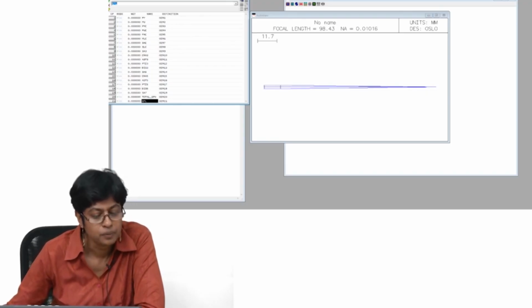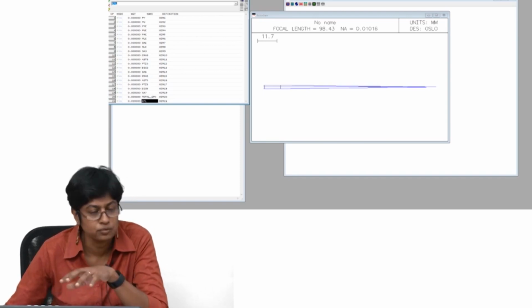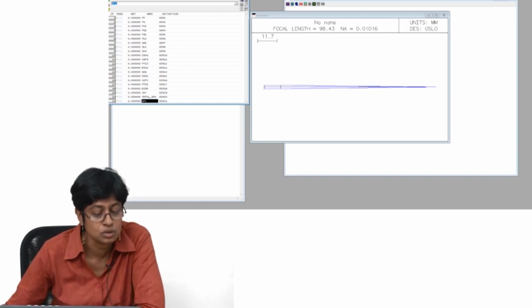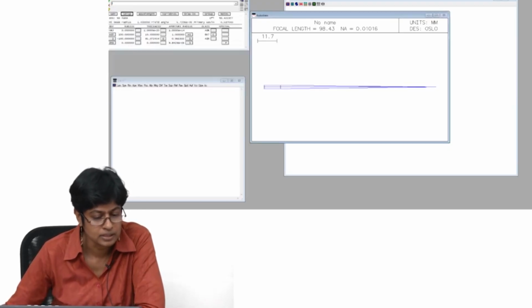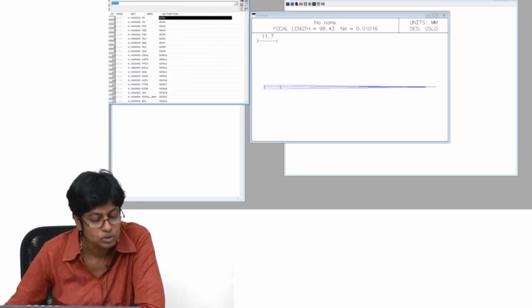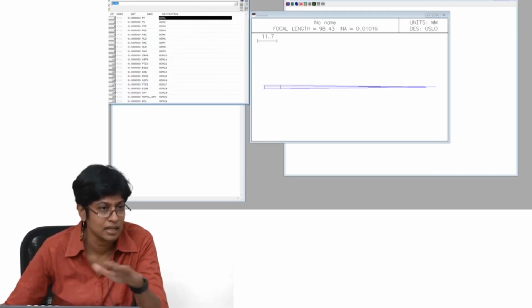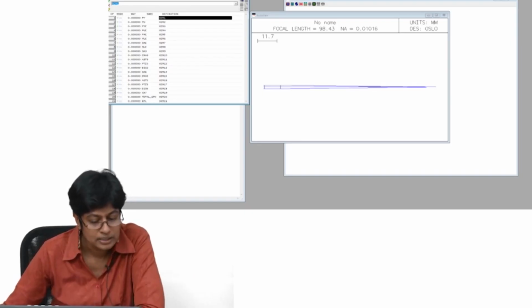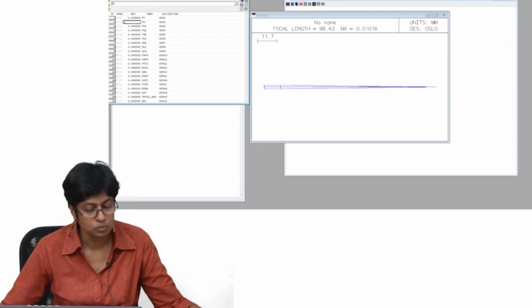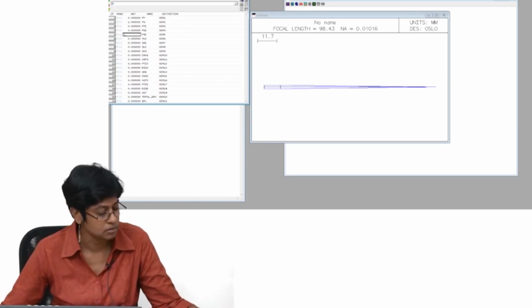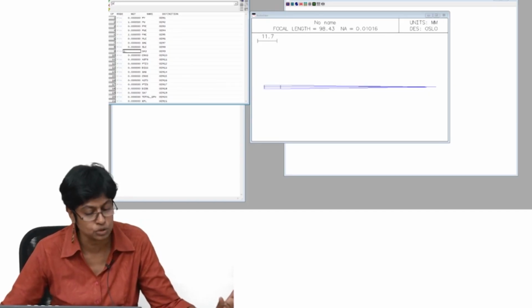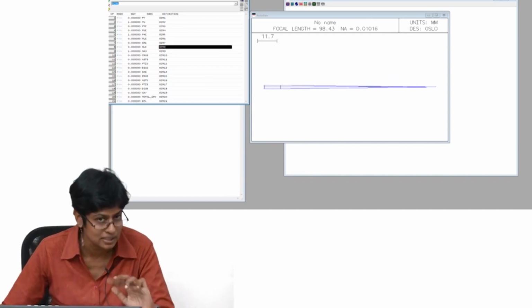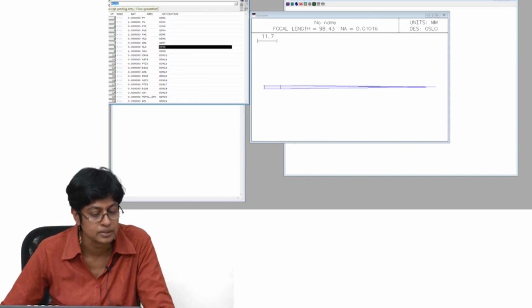Okay. Another point, this is more about how to use OSLO, and it's easier to use OSLO. When you're first setting up your operands, you go through the process that I just did. So, you go to optimize, generate error function, aberration operands. When you do this, it will always clean the slate. Anything you had defined earlier is cleared, and it gives you this. Right? So, let's say we choose PU and we want to reduce some aberration. So, we have given all of these weight 1, that means these are the operands we want to work with. You accept this.